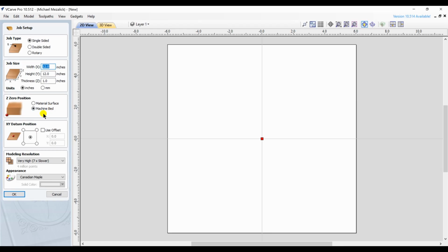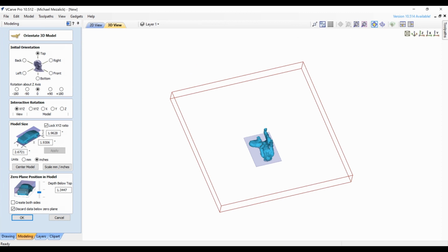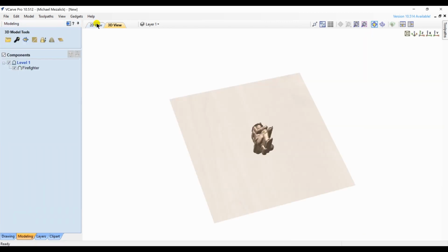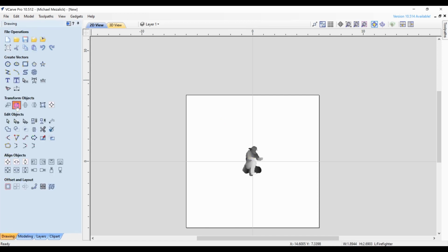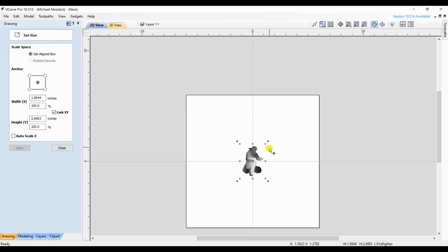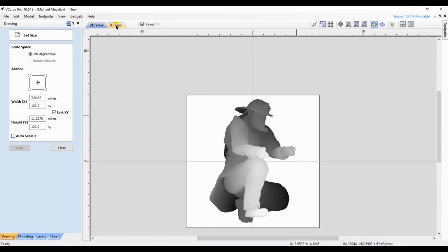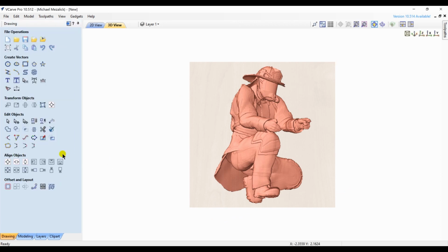Not all 3D software can create the G-code, and that's the difference between a CAD program and a CAM program. These are more design, the CAD programs. And since I'm so used to the Vectric software, it just made perfect sense. Use DAZ for designing of my figures, import them in, generate the toolpathing, and off we go to the machine. So, there's our model. Rather quick, rather easy.